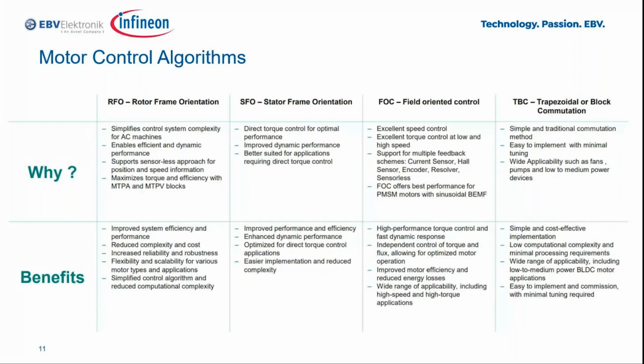By choosing RFO for position and speed control without sensors, we can realize an efficient and non-complex design. With similar logic, if we make a choice for torque control, we can choose SFO, stator frame orientation. I think there is no need to talk about the details of FOC nowadays. Anyone who Googles the topic of motor control comes across this control method first.